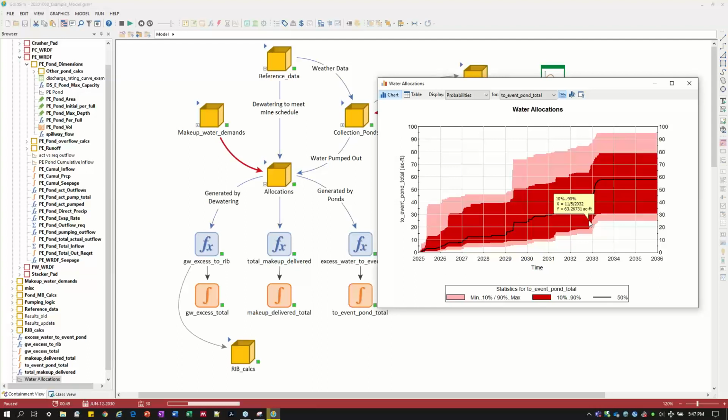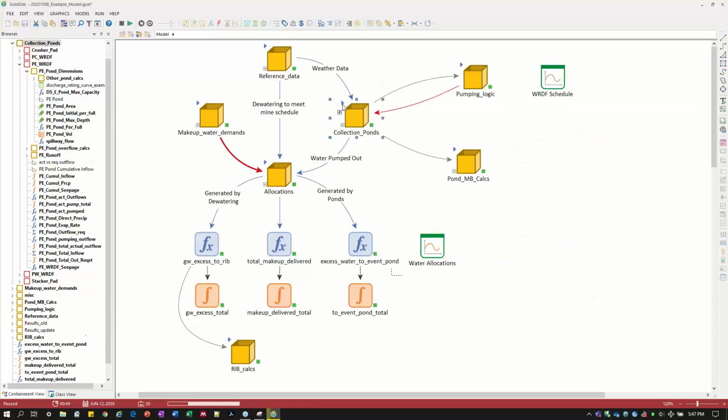That's information you'd want to pass on to the engineer. You'd want to coordinate with the team responsible for developing these types of process facilities, or risk management in general. It's, hey, I have this potentially impacted water that I've got to route somewhere or handle somehow. And that's where the trade-offs get interesting between the amount of land that's available to make the systems bigger. Do we have to now move this waste rock pile? Do we have to push it up the hill?